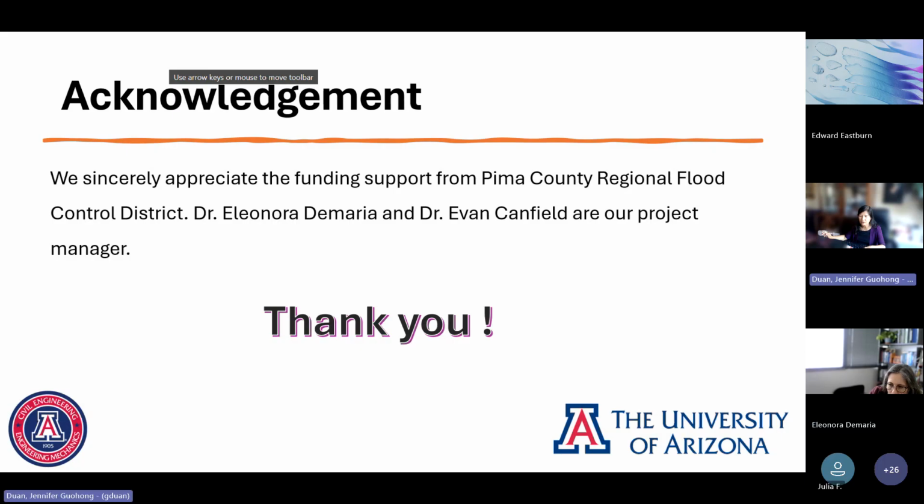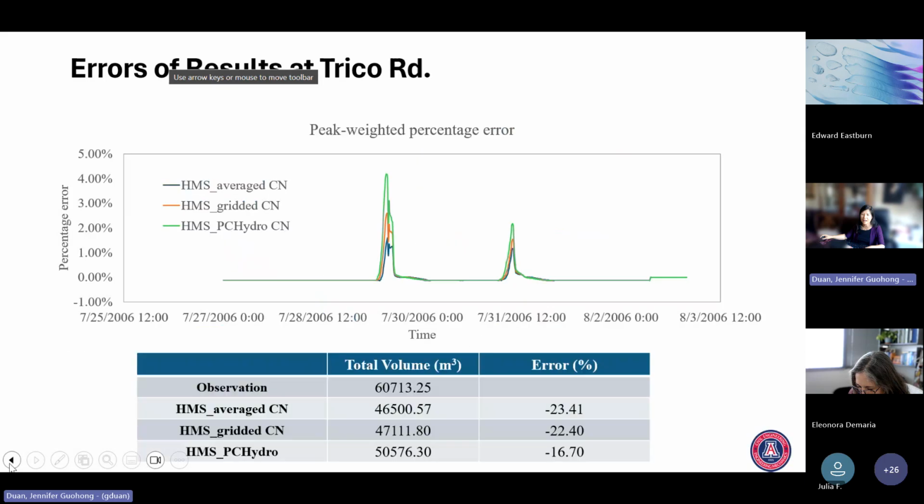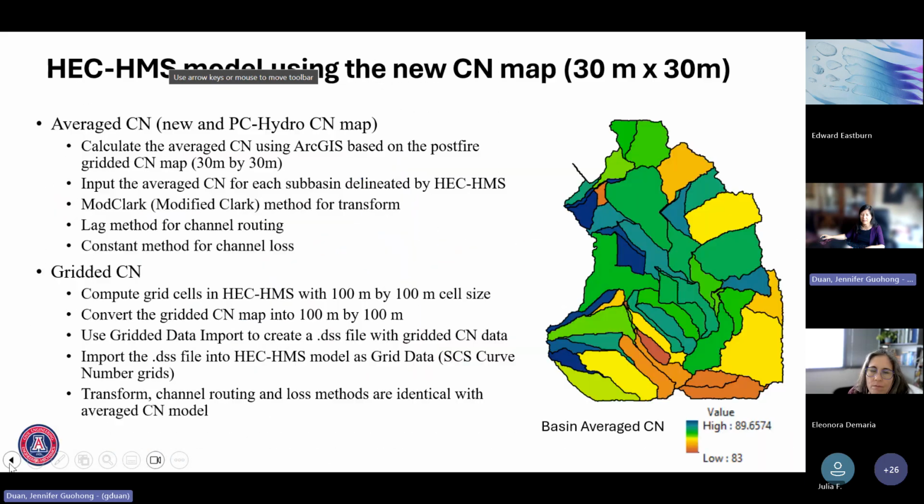Yeah, so you account for ponding water for what? You account for ponding water to calculate the peak flow. Yes, in their model they reduced the flows by a certain fraction, to say that a certain number of backyards simply won't discharge because people capture all the water. Yeah, exactly. So I'm going to come back to right here.